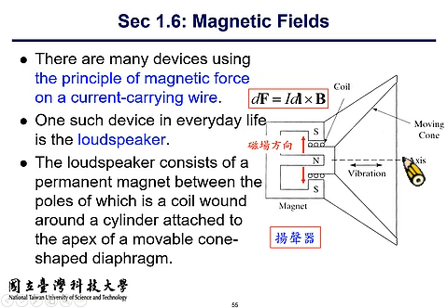The microphone changes acoustic wave into an electrical signal, a voltage and current signal. And the voltage and current signal is sent directly without any modulation. Modulation is a must in current modern communication skills, but surprisingly for landline, there's no modulation. The acoustic wave is transformed into an electrical signal and sent directly to the other household.